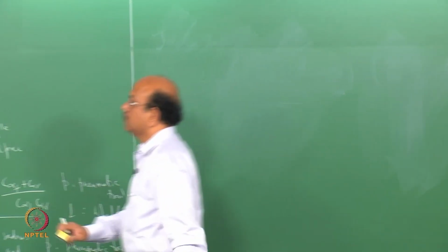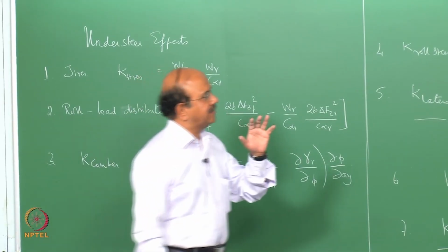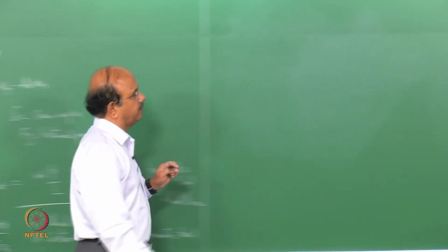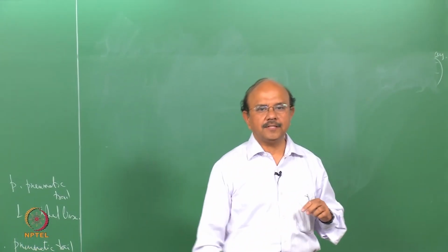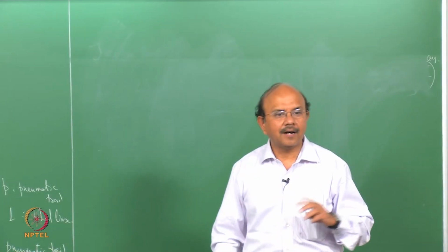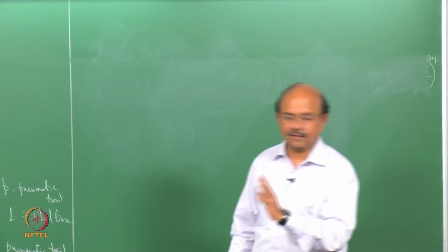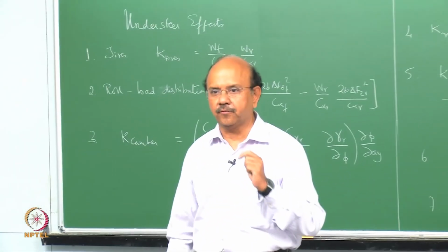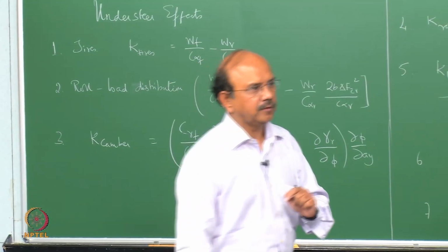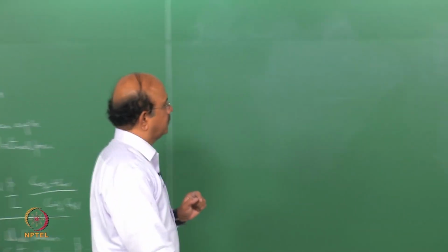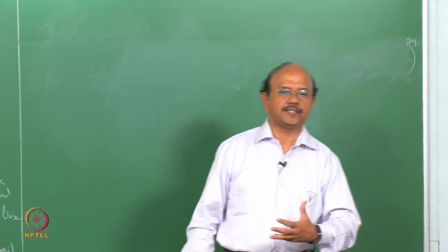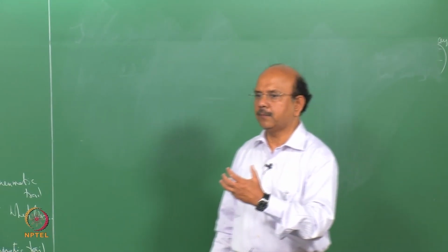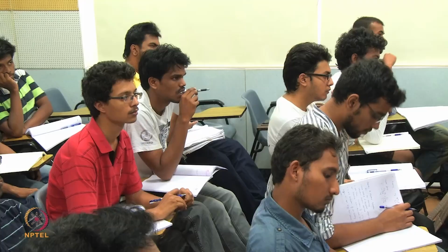And all these roll steer and so on, are they derived only for the steady state case, or is it general? Yes, that's a good question. We had started on this. Understeer and oversteer, all these things are derived for steady state. That's why we introduced what is called transient understeer and transient oversteer. This becomes a very important test for subjective evaluation. In fact, it becomes so important that there are power on tests. That becomes the bread and butter of some of these tire companies.